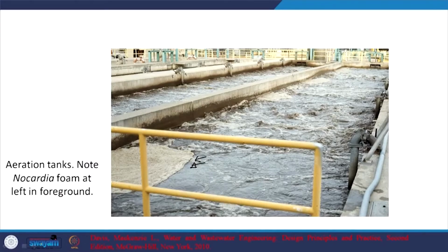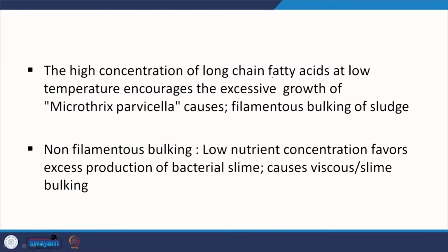Another aspect is that because they are going to stay afloat, they are going to spend more time in the tank. That means these kinds of microbes typically have greater cell residence time, and that can lead to some issues. And again, different kinds, as in long chain fatty acids at low temperature, we discussed this.